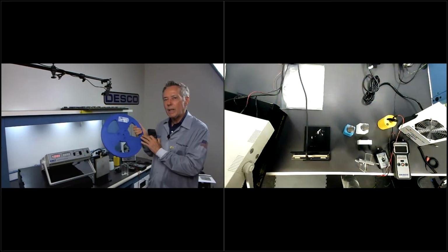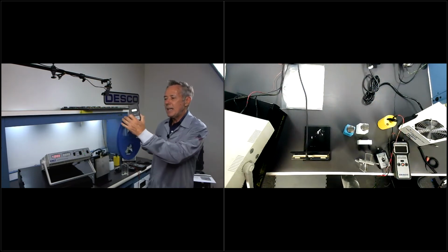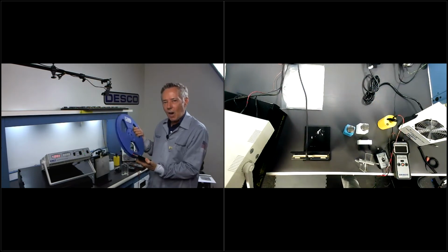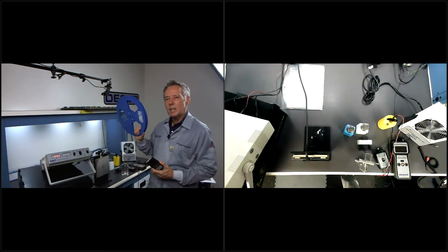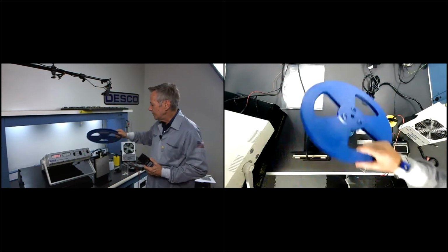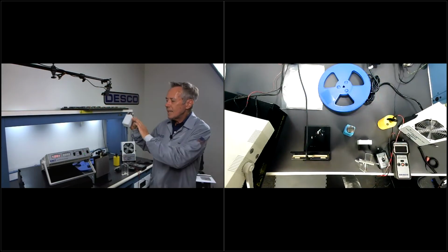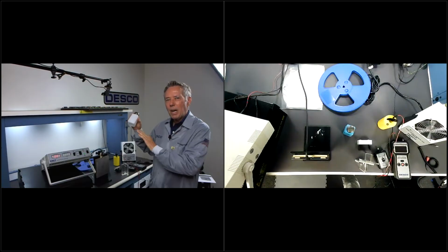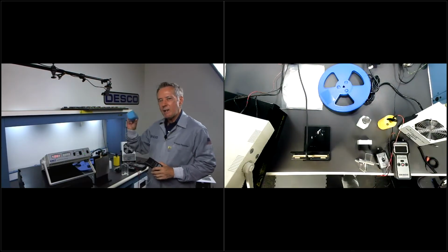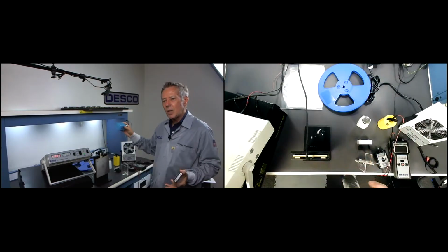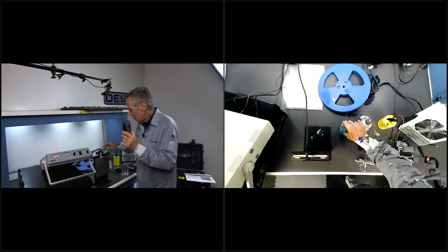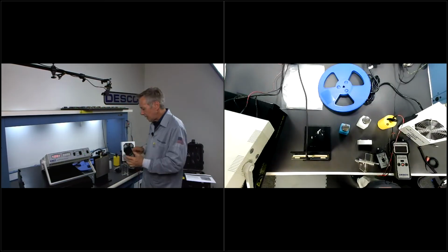In the case of this reel, though, I can't move it. My ESD parts are going to be right on it, if you will. So this is what we call a process insulator, a process required insulator. This thing also is a static generator, but I can just buy an ESD safe version of it. So I can get rid of that and buy the ESD safe one. So there are non-essential insulators and there are process required insulators. We use our field meter to measure those insulators.